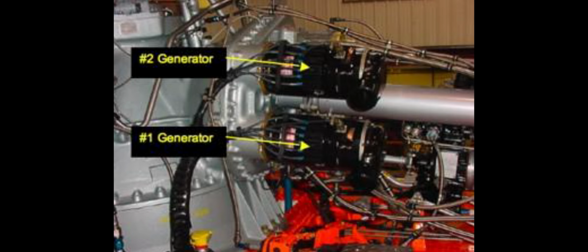The generator contains three main-phase generator windings, a permanent magnet generator, and exciter windings. The exciter windings provide electromagnetic induction into the main generator windings, eliminating brushes and commutators to reduce heat, maintenance, and radio interference. Generator switches. The generator switches are located on the master switch panel on the center console.